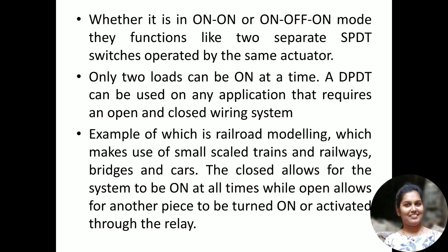Whether it is on-on modes, they function like two separate single pole double throw switches, that is, SPDT switches, operated by the same actuator. Only two loads can be on at a time. As we have two poles here, that is, it is double pole, two poles will be in action at any time. That is, only two loads can be on at a time. Though we have four different connections here at the output side, only two will be in action, or two will be on at a time.